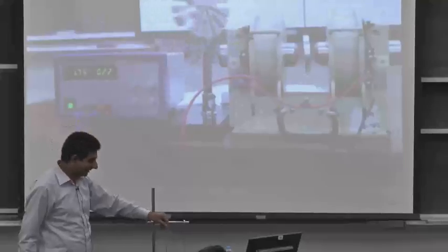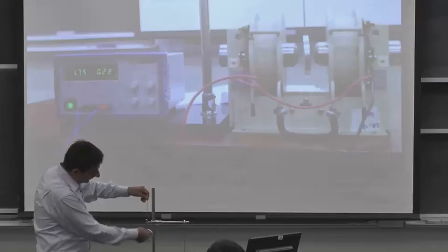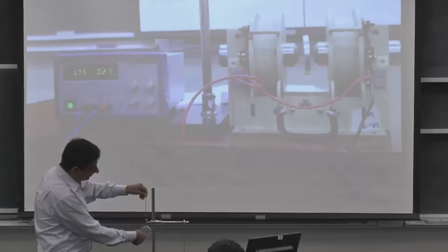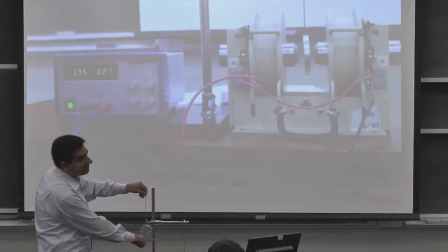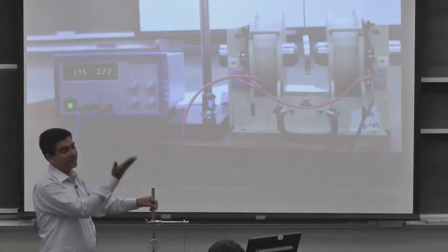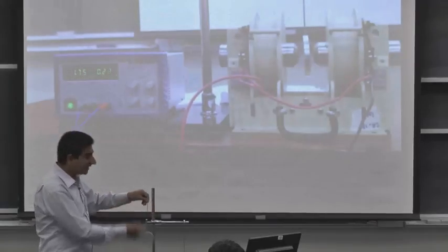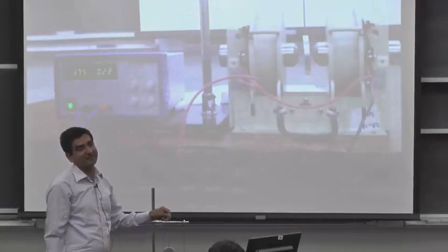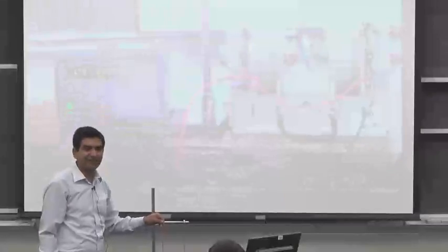Alright, now this disk is variegated, or it has these corrugations, or it has these incisions into it, so that if eddy currents are made to pass, these eddy currents encounter insulating barriers of air. So the conductivity of this medium, or the resistance of this medium, is higher. The conduction, or the inverse of the resistance, is smaller. The resistance is high, so the eddy currents will not be able to produce a strong enough opposing flux. So eddy currents are being arrested in this medium. So the damping will be less significant. So let's try that out.